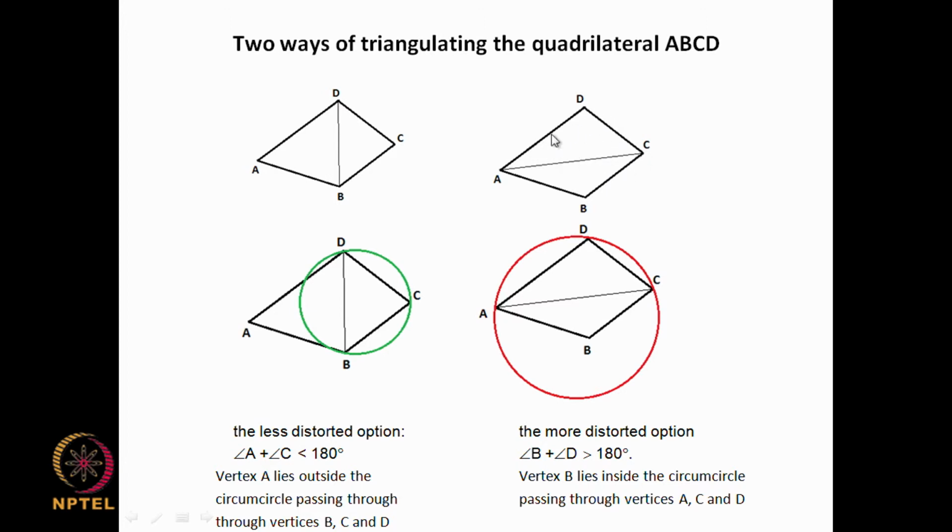So, this particular combination results in a high aspect ratio triangle rather than this one. So, in this, these three sides have an aspect ratio which lies close to 1 for this triangle and for this triangle. Whereas, if you make it like this, then you have this length which is much longer than this length. So, you have higher aspect ratio. So, this is not desirable and this is desirable.